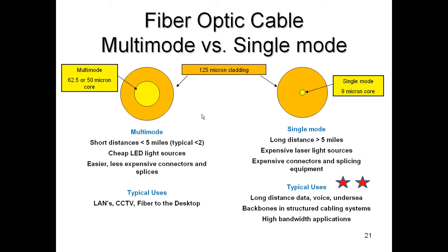So when you're looking at a job, and it's a big job, one of the first things you should ask the owner or the network people or the physical plant manager is, are there any dark fibers or unlit fibers in your cabling system that we can use to connect up our security devices? And if they'll let you use them, you know what? You just became a horizontal Superman. You just went 1,000 feet and you got there like that.